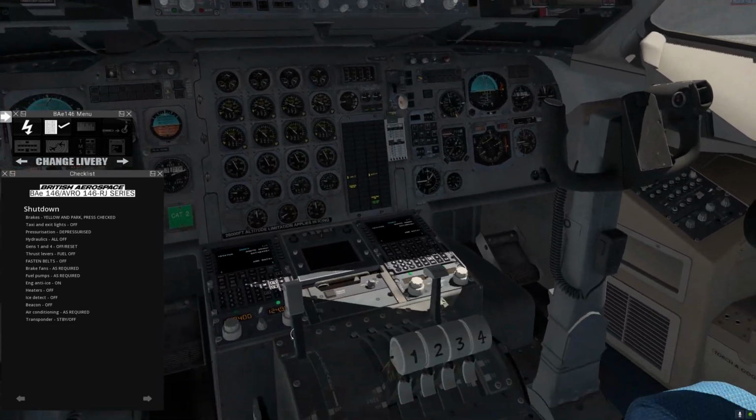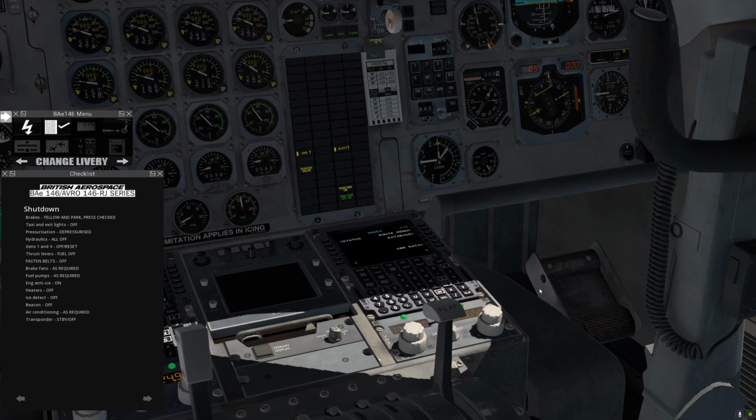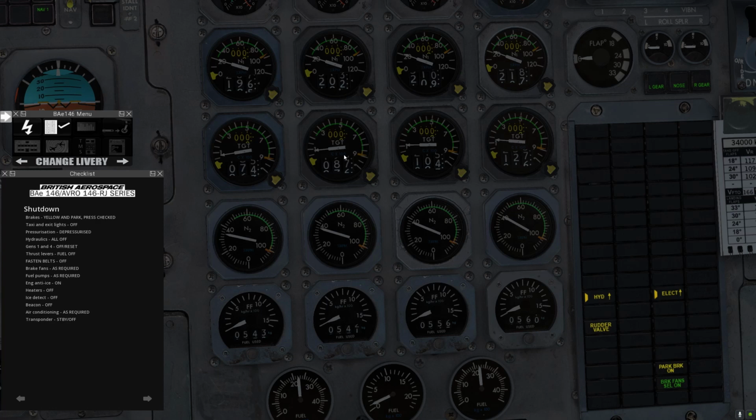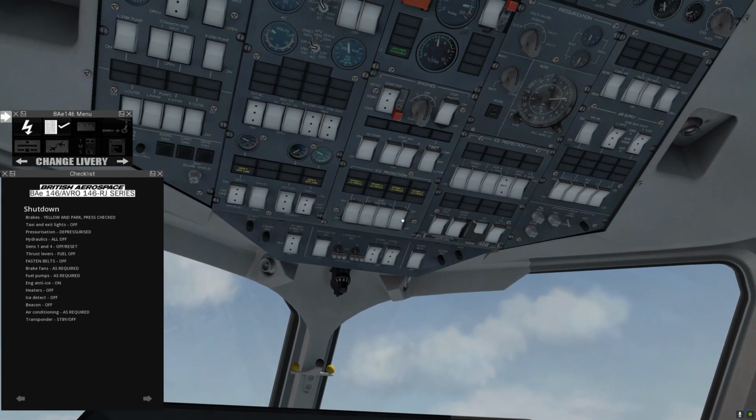Thrust levers, fuel off. So we'll go lever, lever, lever, lever, and off, off, off, off. And we're just going to verify we see the temperatures all falling. We don't have any that are kind of hung. Seatbelts sign, off. Engine anti-ice goes on. This is for the next start. Heaters, all off. Two clicks for that one.